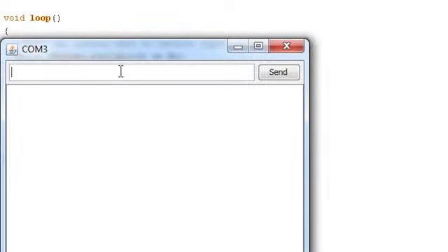We have our Arduino plugged in via USB on the other end. There's nothing connected to it, just the Arduino. We just want to test the serial functionality. So if we send it a 1, we should get a 1 back. What? A 49? Oh, that's weird. What happens if we send a 0? 48. Huh. That's peculiar.